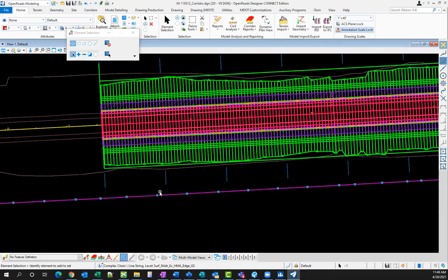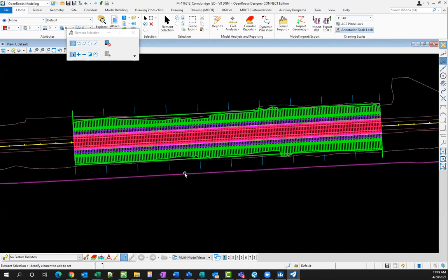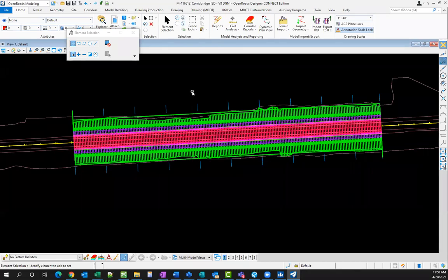the survey that we have here, in my case, it's cross sections every 50 feet. So we have cross sections every 50 feet, but we're modeling every 5 feet. I just don't see how much benefit there really is to having all of those extra points in there. So just something to be aware of, something to look out for. I know it's happened on a lot of projects, and it's not something that's easy to fix after the fact. So just pay attention as you're going through the modeling process and taking a look at how often things are processing, keeping in mind downstream users who are using the data.